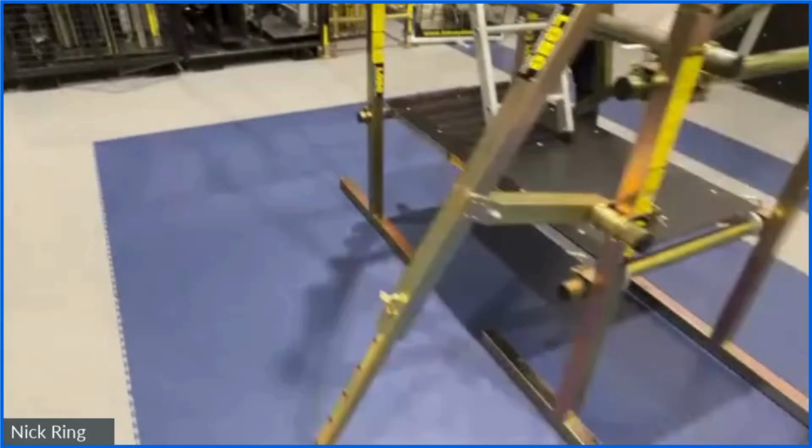So now we have 0.9, we have 0.8, and 0.9. When you add those three dimensions up, the new base of the system is 2.6 meters. And then you times it by 3, because that's the safety factor, and that means you can stand all the way up there at 7.8 meters.